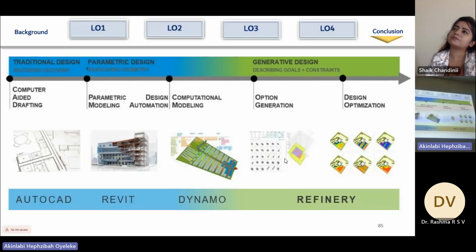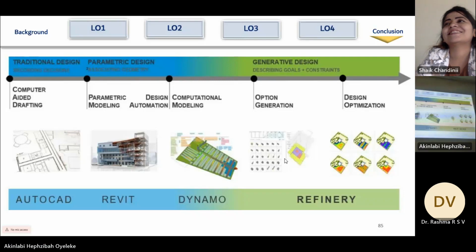For example, if you have two ellipses and two circles joined by this conveyor, if you alter the diameter of this and maybe you make it bigger, this element is going to automatically adjust itself to suit this constraint. So that is one simple way I can define or explain parametric design.